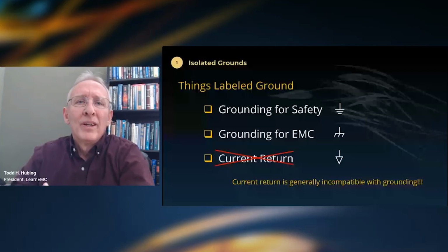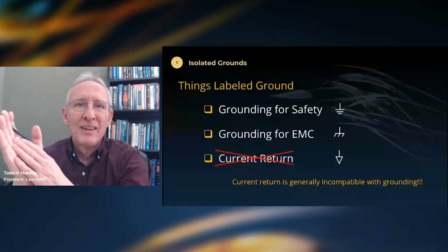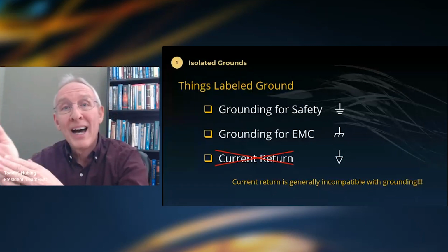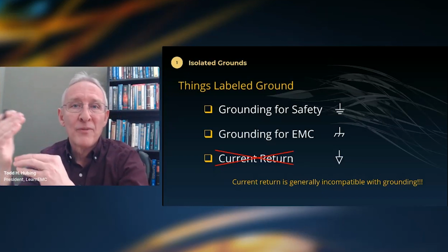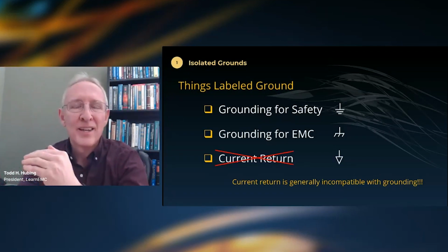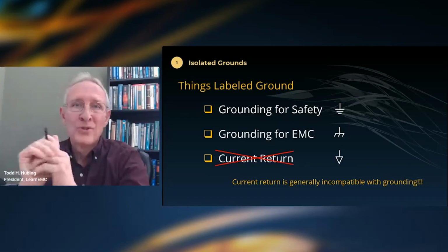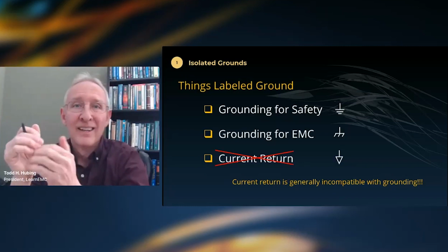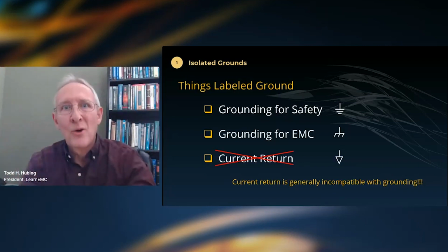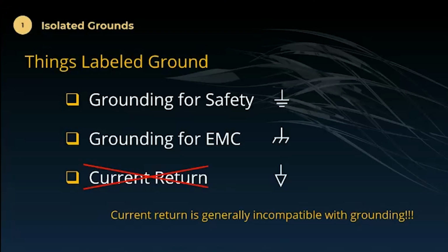In your home, you may have an outlet that has a hot, a neutral, and a ground conductor, where the potential of the hot is a voltage in the US, 110 volts, say, RMS. The neutral has a voltage of 0 volts RMS, and the ground has a voltage of 0 volts RMS. And actually the neutral and the ground wires go to the exact same place. But they're different. And the reason they're different is for safety reasons.